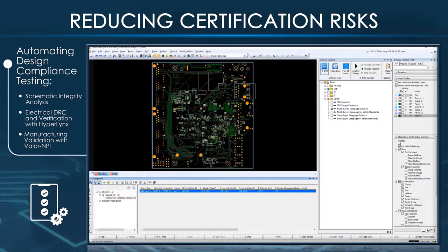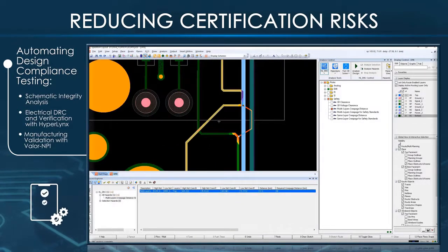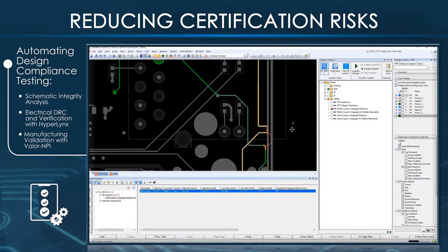Another example is the board edge. So we have that khaki 100-volt trace on the top side of the board. And we can see that it's actually creeping around the edge of the board and affecting a net on the bottom side of the board.